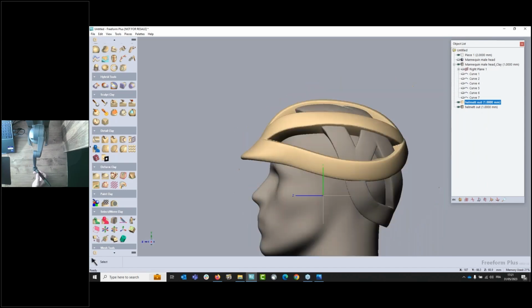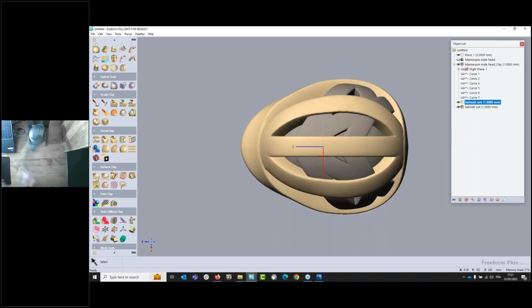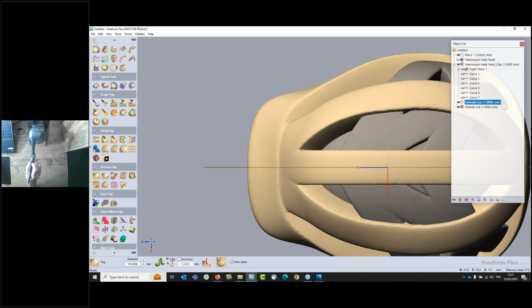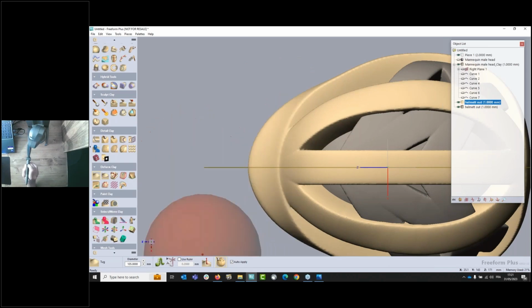So I will use another deformation tool. Let me rotate the view. I will use the Touch tool. The Touch tool allows me to take any part of the model. And because I'm working on a voxel base, I can deform everything with total freedom. To see what will happen, I can ask for a symmetry, because here I cannot see the results. But if I activate the interactive symmetry, I can do it in real time. I will just activate an axis snap to be sure I will move only in one direction. Then move this one like that.